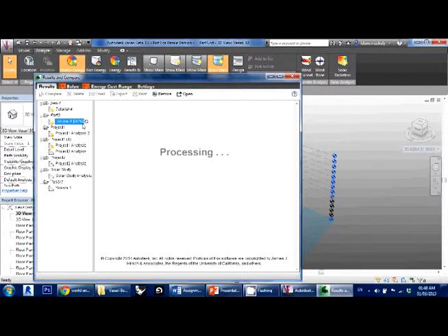You have to know that the energy simulation and the solar radiation are made on the internet. They're not made on your PC, so you have to make sure that you're connected to the internet. Now we'll leave it until it reaches 100%, and we'll start seeing the data.